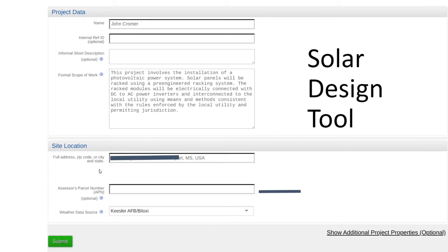A good solar project should not be installed in an area that has significant shading. And partial shading is essentially resolved through module level panel electronics. So without further ado, let's get into the design example.